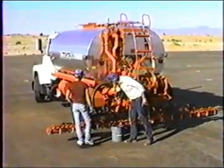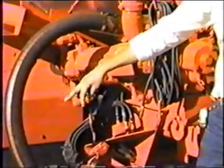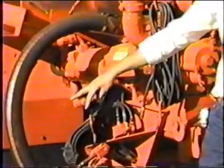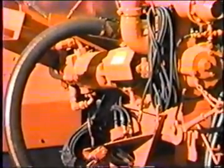Okay, down on the side, there's a pair of valves. They're called a lockout valve. It's a hydraulic valve that prevents flow from the hydraulic cylinder unless it sees flow initiated by the valve that's controlling that cylinder.